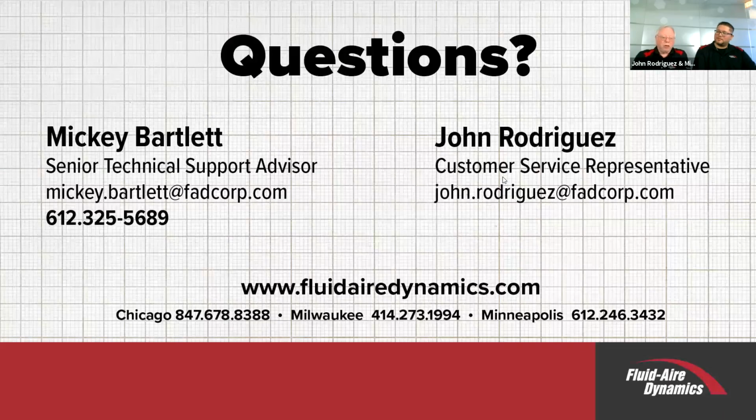Again, the cooler it is, the better your dryer will work, and the better your machine will work. Your machine should be running at around 180 degrees oil temperature. The discharge temperature is going to be 15 degrees above whatever the room temperature is, and as I mentioned before, 20 degrees above. So if you have a 105-degree room, you're going to have 120-degree air coming out. Your dryer's got to be twice the size.